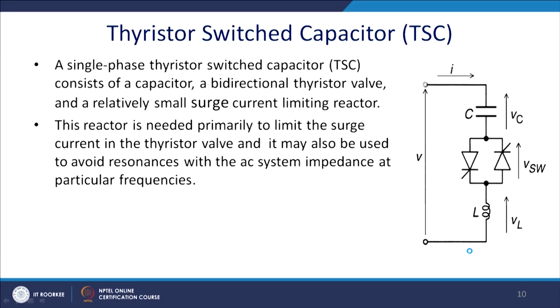Now let us see another shunt compensator, that is TSC, thyristor switched capacitor. A single phase thyristor switched capacitor consists of a capacitor, a bidirectional thyristor valve, and a relatively small surge current limiting reactor.